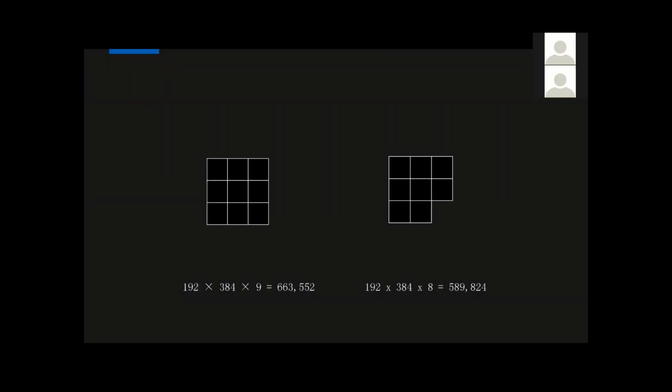But actually, in our control system, the algorithm for calculating the loading capacity per port always uses the minimum rectangle that covers all the panels on this port. If you pay attention to the connection here, the loading capacity on this port is still 9 panels. Even though the 9th panel is not actually connected, we're calculating based on a rectangle, so it's still calculating 9 panels in total for the loading capacity.